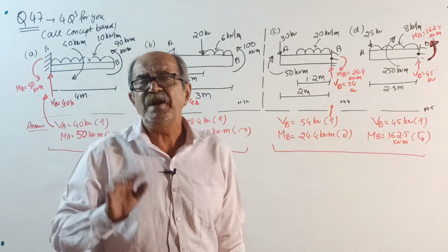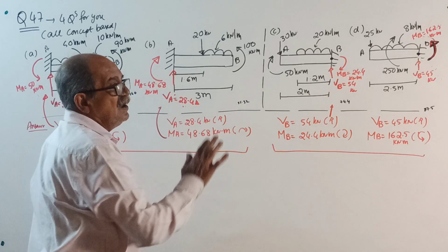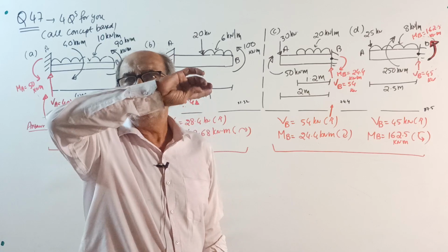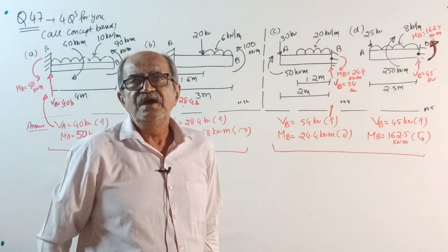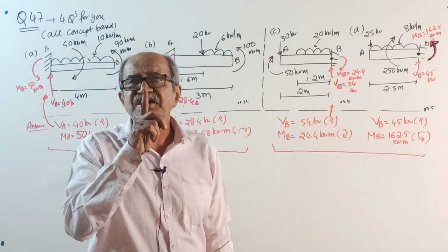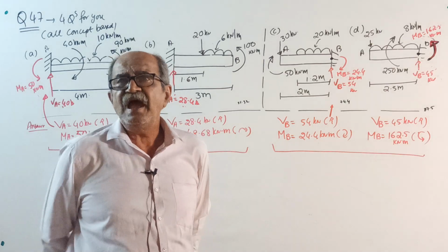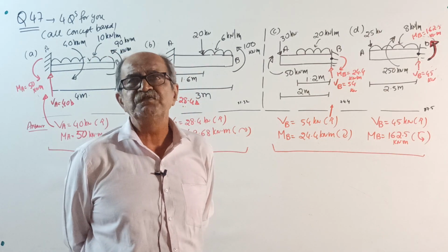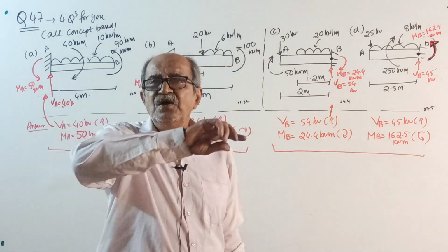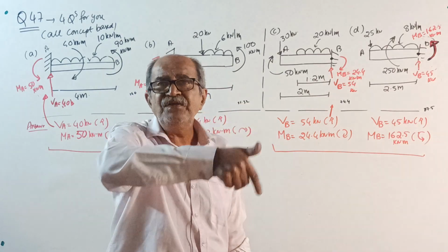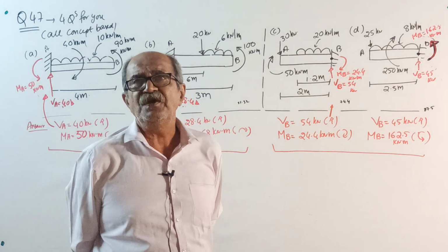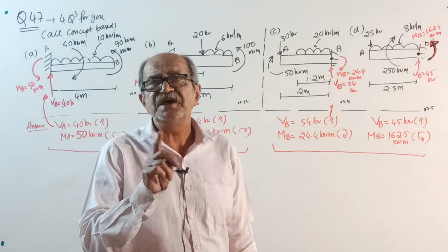Now, reacting moment. Don't bother with these two. Always comes to fixed end. Find the net moment, whether net moment is clockwise or anti-clockwise, about the fixed end, don't by heart left and right side. If the net moment, that is the action I told, if it is clockwise, reacting moment will be anti-clockwise. No plus minus then. Whereas if it is anti-clockwise, reacting moment is clockwise.